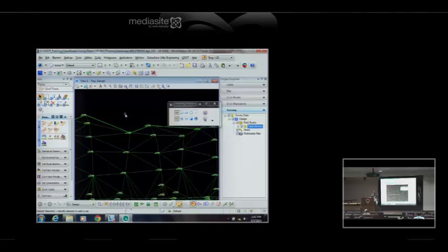So you don't really know where that annotation is; it's just a display. I view the features in this release as more of just showing me what's there. If I needed to display contours in this release, I'd go through the trouble of exporting it to GEOPAK V8i, and display the contours using the DTM preferences. That's what I would do, just because of the way the text on the contours is handled in this release.